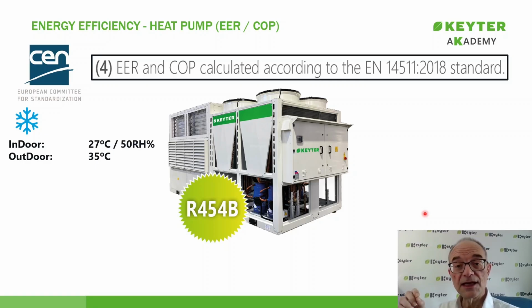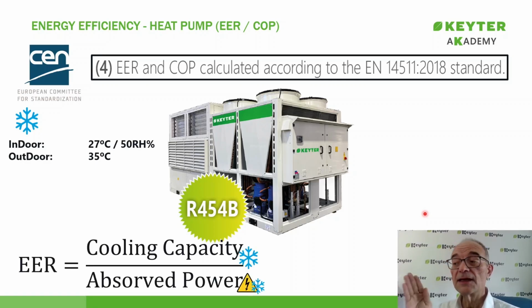And calculate the EER as the ratio between the cooling capacity delivered by the unit, or the energy delivered by the unit over a period of time, since the test involves not just an instantaneous moment, but you have to keep the unit operating under those conditions for a certain amount of time. So as we've said, the EER for cooling mode would be the ratio between the cooling capacity delivered and the electrical consumption of that heat pump operating in that mode.